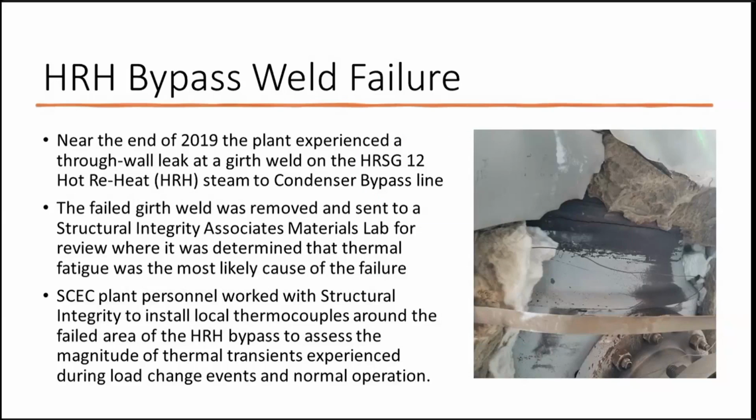So the site was concerned. Two years after commissioning, we already have a through-wall girth weld crack, as you can see in this picture below. We contacted Structural Integrity. I was able to send the material sample down to their lab in Texas. The root cause from their lab: thermal fatigue. We worked with Structural Integrity right after that to install local thermocouples. This is just the beginning of the process to monitor the spray.